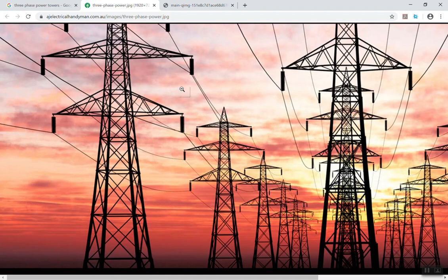Now these are single wire ones still. There's only one wire, but this is where you could have a bundle of three wires attached here, or a bundle of four wires, and those would all still be in the same phase. It's just a way to transmit more power, because you've got four wires in the same phase. And instead of making one bigger wire, having four smaller wires often ends up being cheaper than making one big wire.